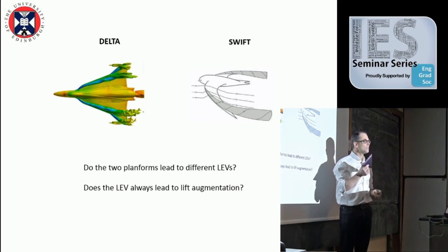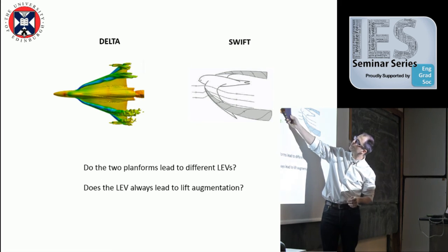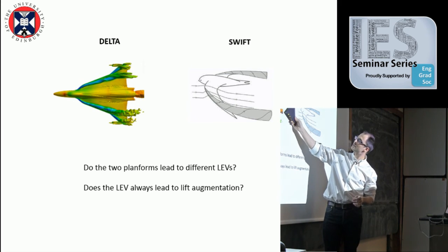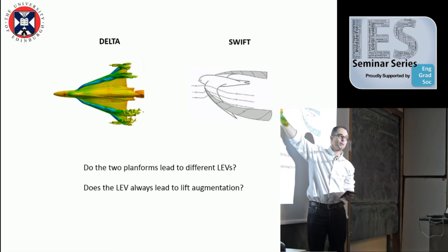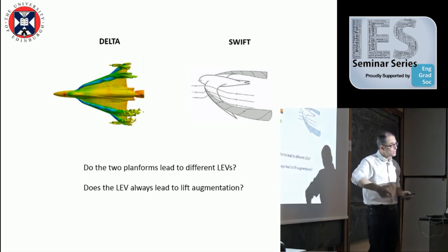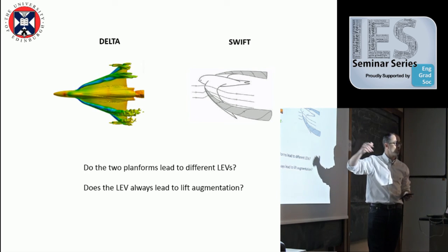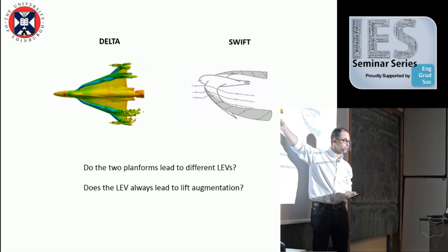And the vortices that you generate could actually not be shed, could potentially remain attached to the foil, which is very interesting. This is what you see here. The concept of delta wing is this one. This is your jet fighter, this is your delta wing. And what you see is that you're generating a vortex, but the vortex is always there. It's not like a trailing edge vortex that you're generating and this is gone back behind you, would just be dissipated in the wake. This vortex remains here.